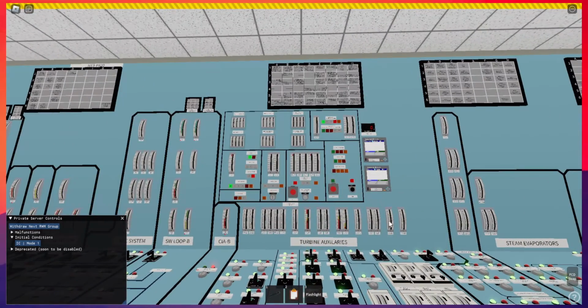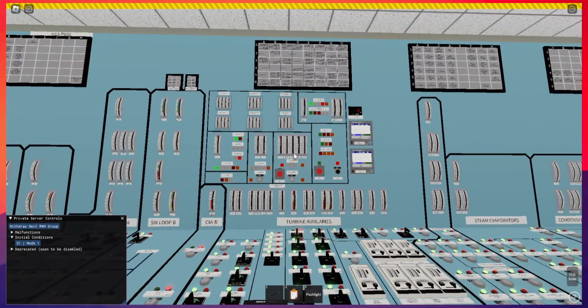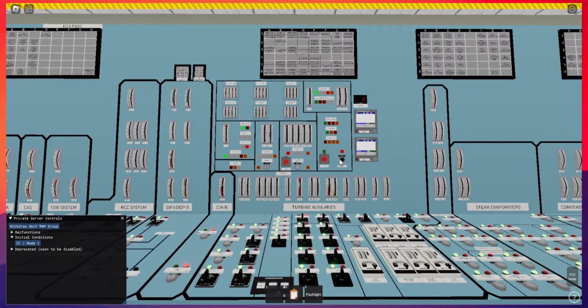Over here, the electrohydraulic control unit, the EHC, is the unit that controls all the electrical and hydraulic systems for the main turbine generator and the main turbine itself. This means all of its auxiliaries, so that will be bearing oil, hydraulic oil, and in this plant's case, the generator cooling, which is hydrogen, I'm pretty sure, hydrogen cooled. We also have all of the controls for load.